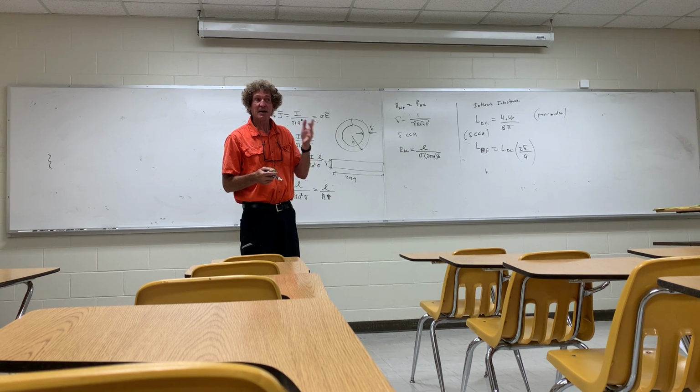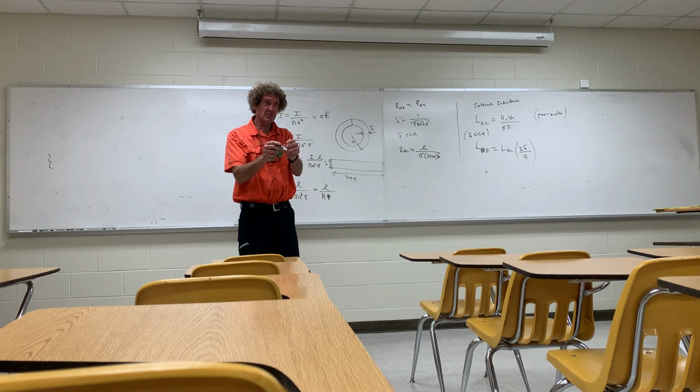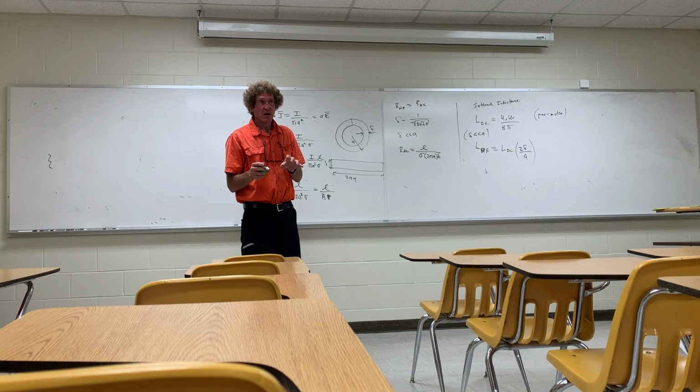That's high frequency. So what we had to do is change the oscillators, and in doing so, we had to go in and unsolder and resolder and then re-engineer the circuit. There's more to this than I'm saying. Well, at high frequencies, even if I put my finger in there, it changed the resonance. I found that. And this is very troubling. So we had to get dielectric screwdrivers.